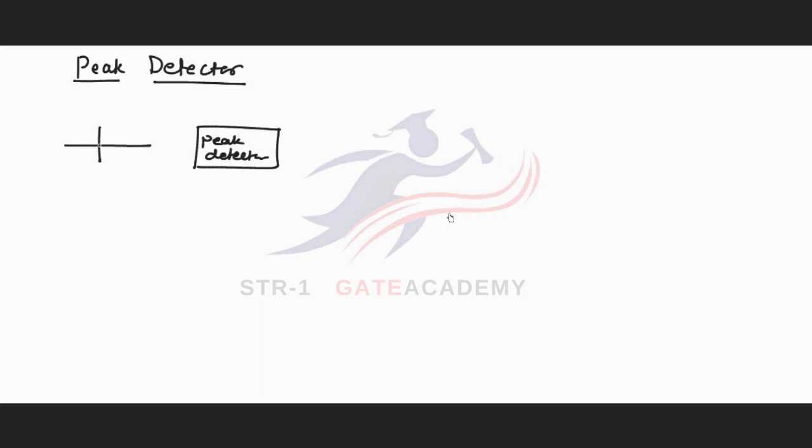and we have applied an input waveform to this, Vm. Then this peak detector will give a constant output which will be equal to the peak of the input waveform, that is Vm. So this peak detector is used to detect or to hold the peak value of the input waveform. The circuit diagram is very simple and it is much like a clamper.